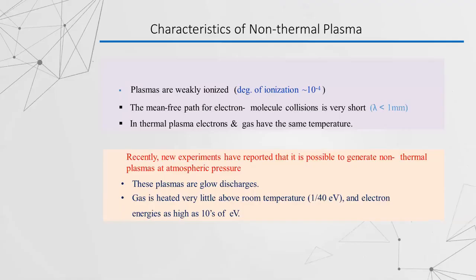Introduction. Plasma can be classified in various ways, such as based on temperature, pressure inside the reactor, and electric signal. On the basis of pressure, plasma can be divided into two groups, atmospheric pressure plasma and low pressure plasma. Everybody is well aware of low pressure plasma as it is extensively used nowadays, for example in the semiconductor industry for computer chip manufacturing. But due to some disadvantages, as it requires an expensive vacuum chamber to generate the plasma, we generate plasma at atmospheric pressure.